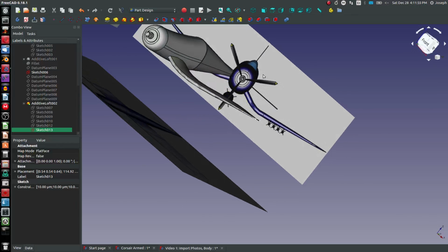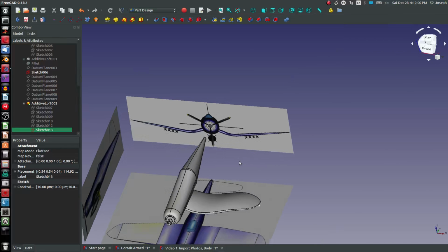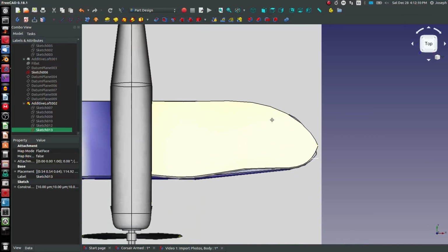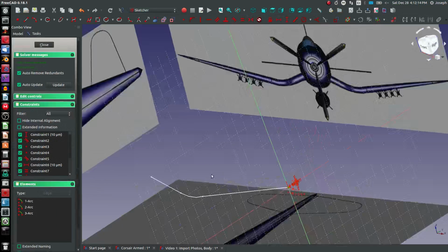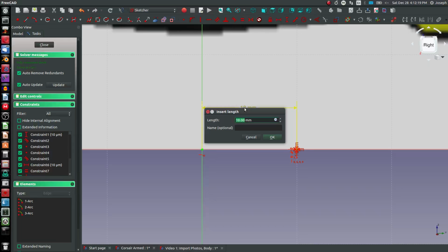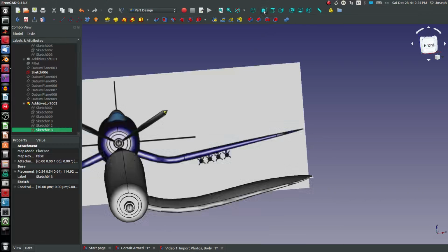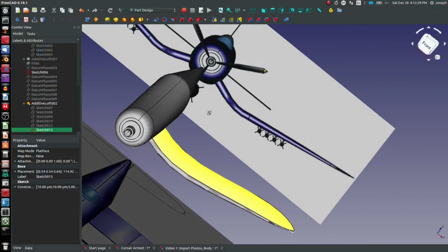And yeah, you know, that's really not bad. Front view seems to match your wing profile pretty well. Although we get that kind of annoying, it's almost like an S shape. So let's go to top view. And that's become more pronounced now that we've changed our sketch a little bit. So let's go 5 millimeters. Well, pretty cool that worked in one sketch, or one loft.